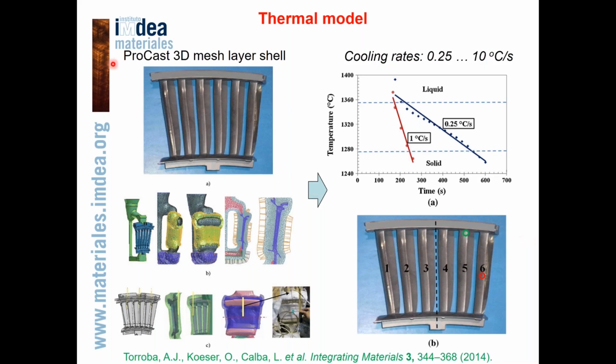They developed a mesh representing the shell mold, and using Procast software they also modeled the filling of the mold and solidification process, and the local cooling rates were calculated for each point of the nozzle guide vane.